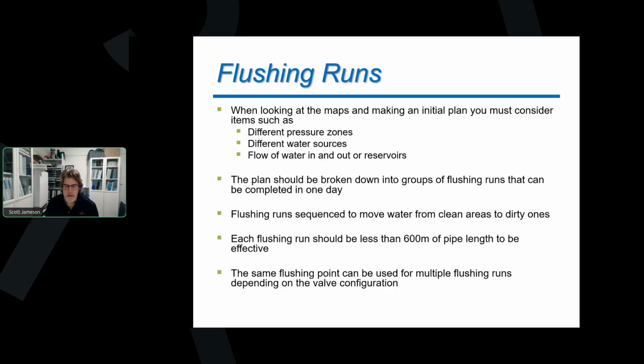500 meters, 600 meters of pipe length, that is what the AWWA recommends again. If you're taking those longer runs, you're not going to be as effective. This is, again, if you're stirring up debris and picking it up off the bottom of the pipe or tearing some slime off the side of the pipe, you need to keep that suspended until it gets out of the main.